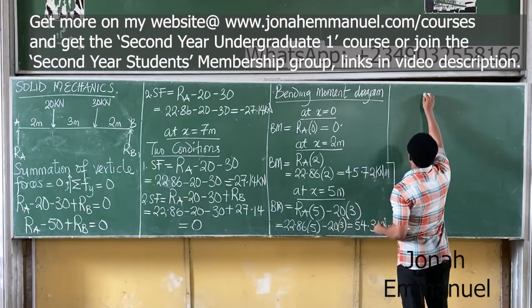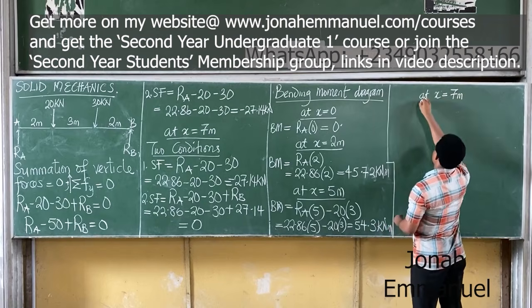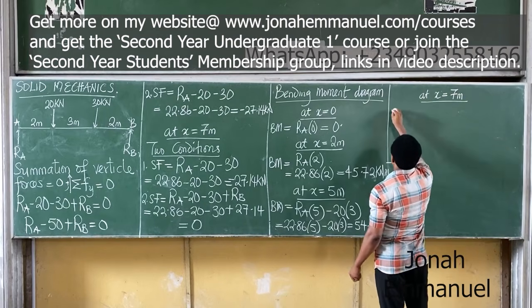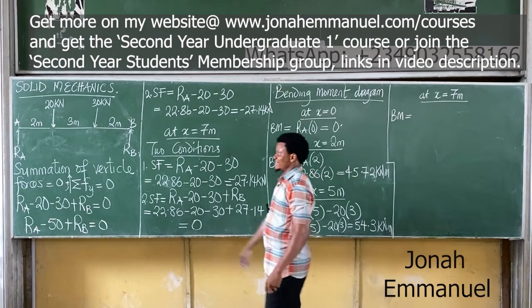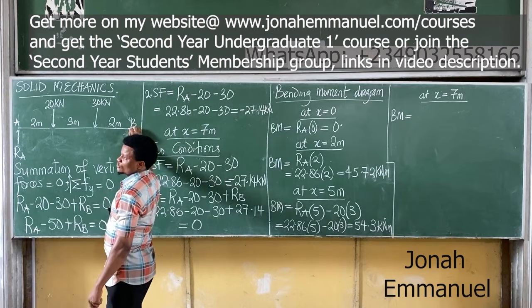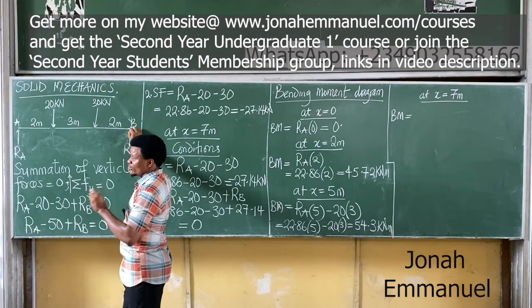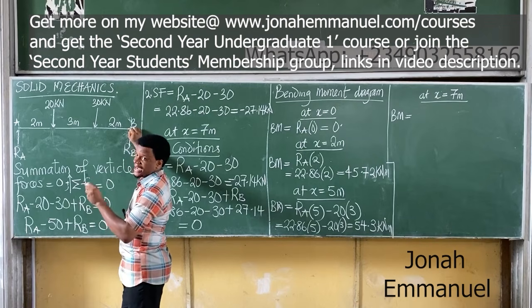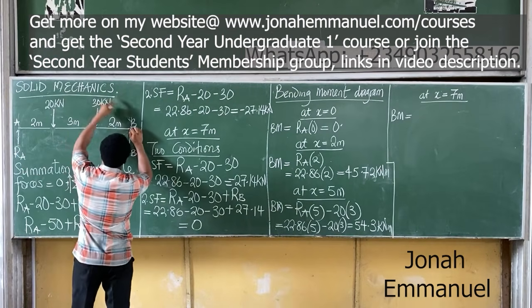Our last point is at x equal to 7 meters. At 7 meters, what is the bending moment? Bending moment at 7 meters, that's here. Now, don't forget, I'll take only the forces before that point. I will not include the force at that point. So this moment here is what there? Clockwise, coming like this, that's clockwise.